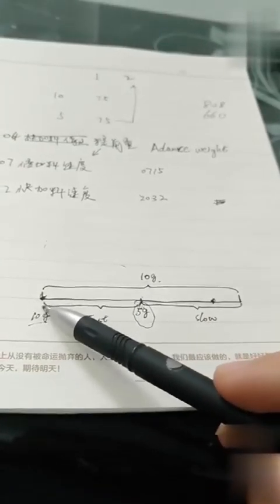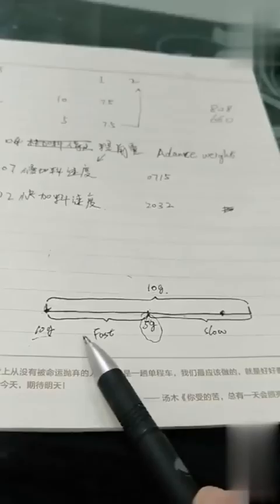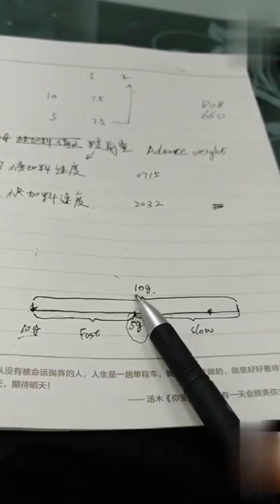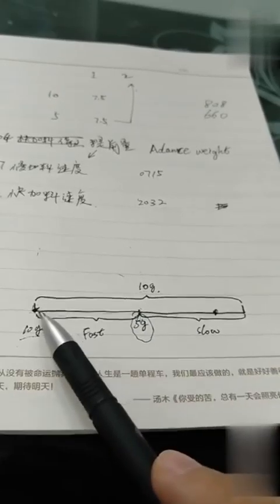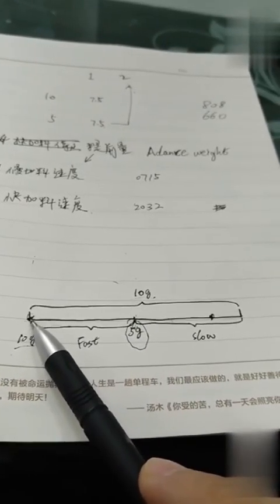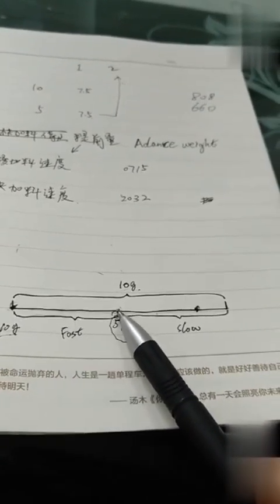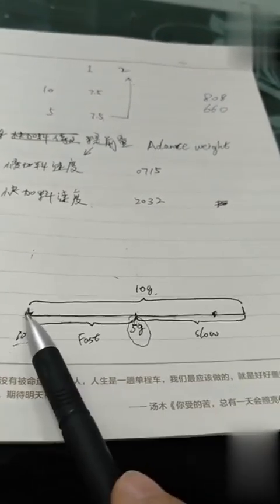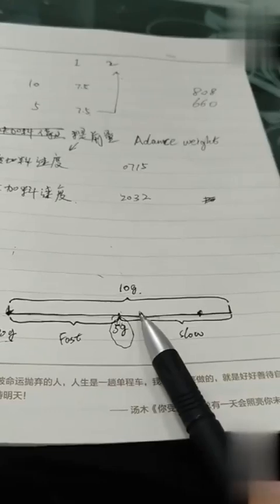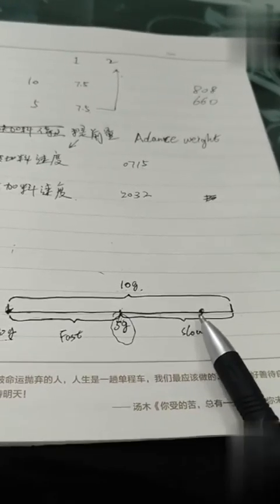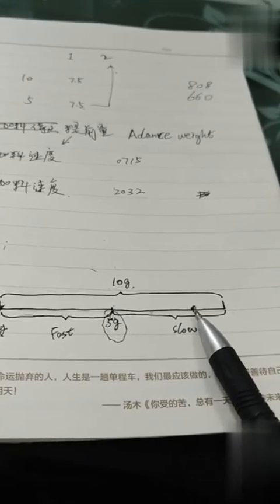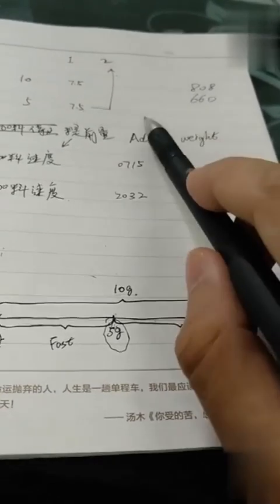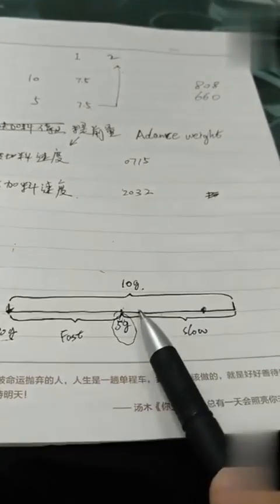To help me explain how this works, I have a little drawing here. Imagine this line here is the weighing process. I set the weight to 10 gram, and then the machine starts to weigh from 0 gram, 1 gram, 2, 3, 4, 5, then towards the end, 10 gram. If you already use the machine, you will notice that this weighing speed is not consistent. At some point, the machine will slow down, okay? Especially towards the end. That's because we set an advanced weight in this machine.